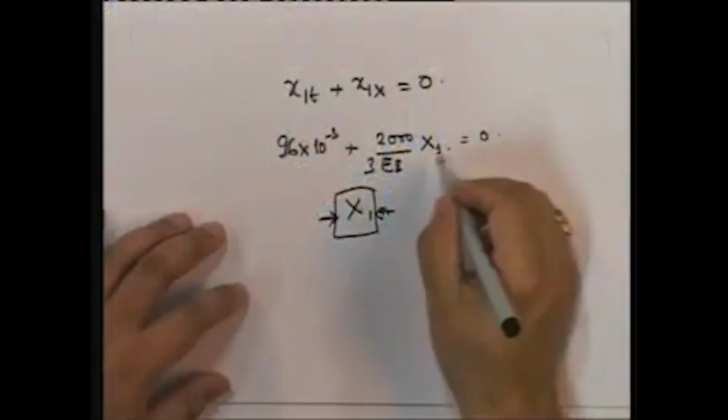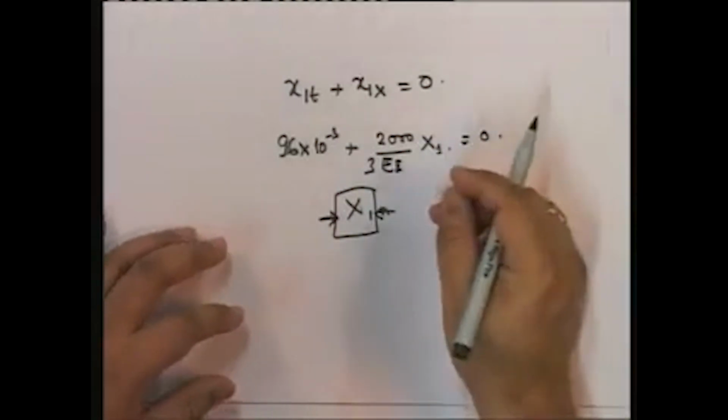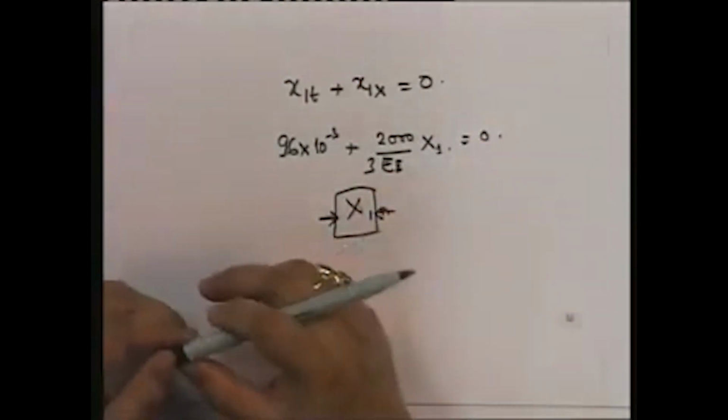I'm not going into that detail because actually, you need to put in the value of EI, etc., to solve for it. Okay. So in a sense, I'm just coming down to how to compute the effects of thermal stresses on beams. Now you may say, well, you've not considered any loading, but again I go back to the same point that I made earlier: if I have a temperature as well as a loading, how would I do both of them together?